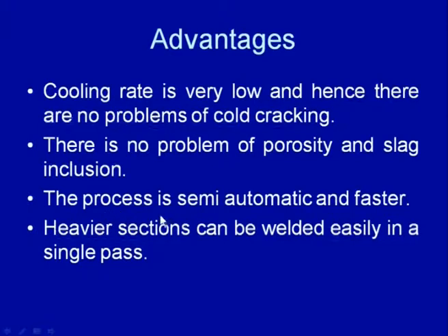So, there is no problem because of the very low cooling rate encountered by the weld metal and the heat affected zone. There is no problem of porosity and slag inclusions in the joint made by the electroslag welding process. Further, this process is semi automatic in nature and faster also. Very thick sheets can be welded in a single pass. So, the process is faster in that way, and heavy sections can be easily welded in one pass.